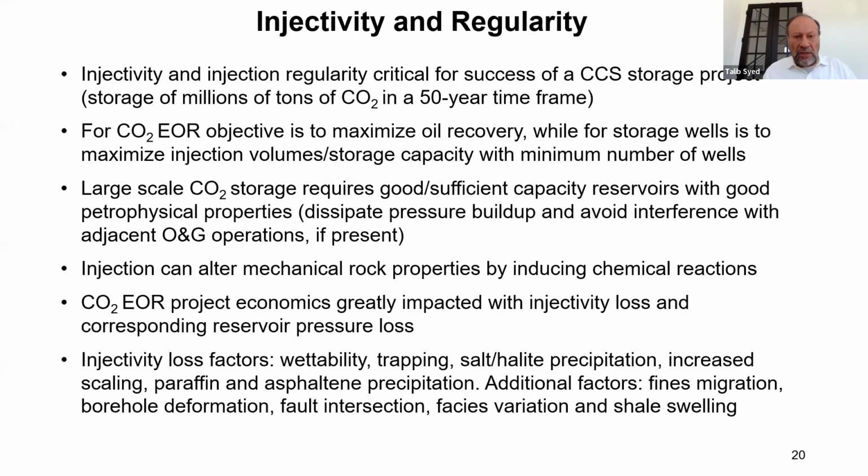I'm introducing a term here, injectivity and regularity, even though that is not related to well integrity, because it's critical for the success of a CCS project. For CO2 EOR, your objective is to maximize oil recovery, but for storage, you want to maximize your injection volumes and storage capacity, but using the minimum number of wells. So injection can alter the rock properties by inducing chemical reactions. And injectivity loss factors could include wettability, trapping, salt halide precipitation, etc., as listed here.